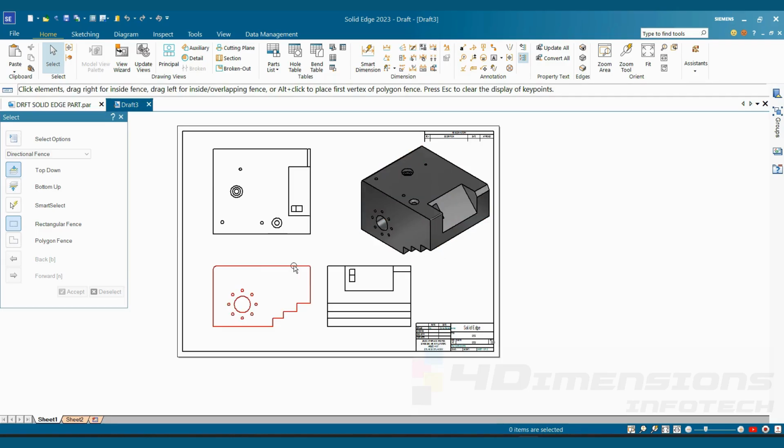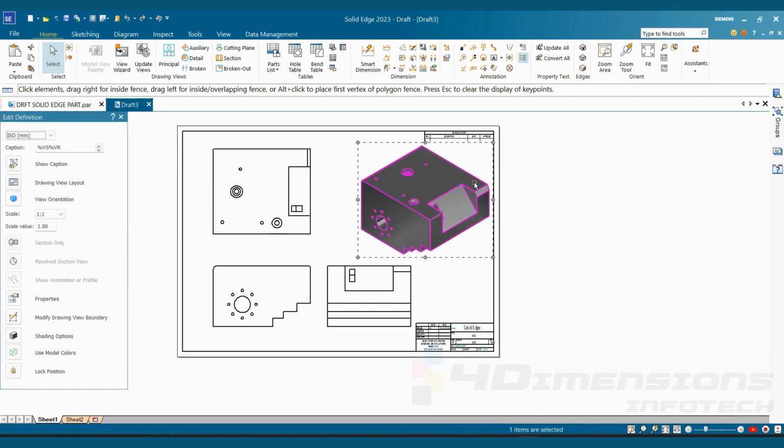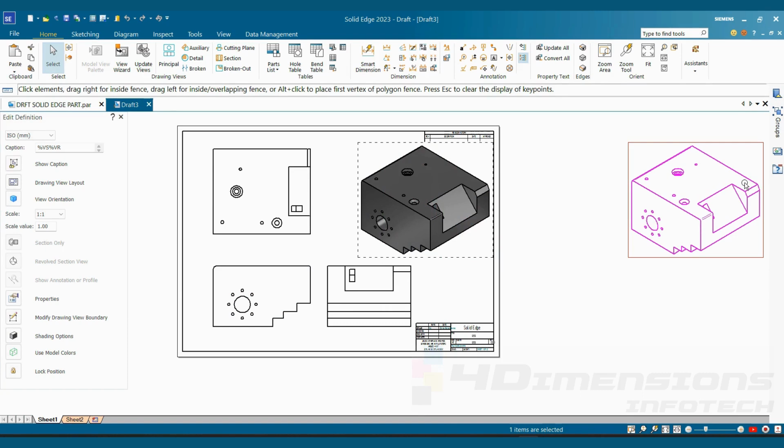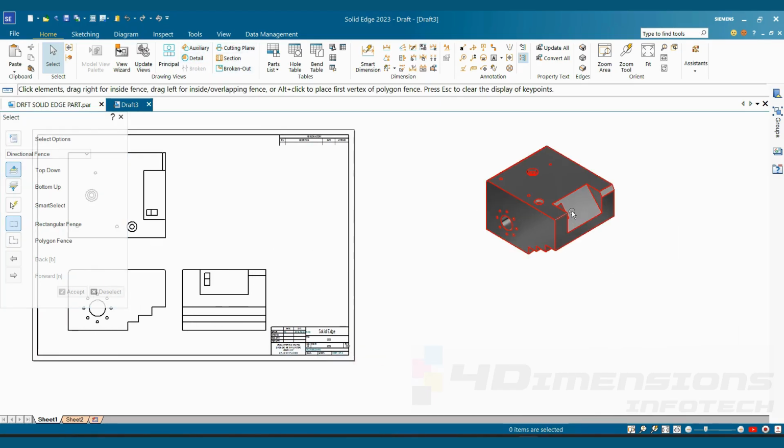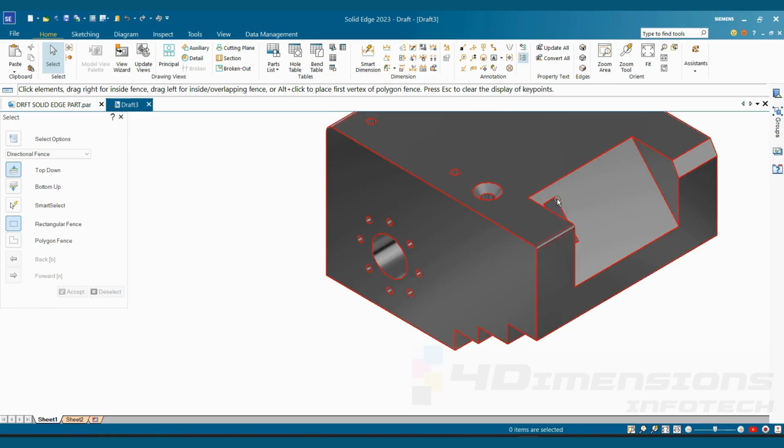Now in sheet 1 auxiliary view, I'll just click and drag this view, isometric view, a little bit aside so as to take the auxiliary view of this front view. So now auxiliary view importance is just that if you are having any incline cut, you can see here this incline cut and one feature is being cut out there.